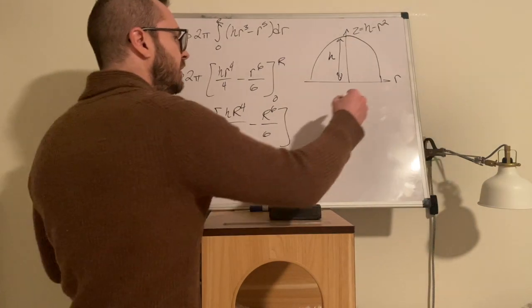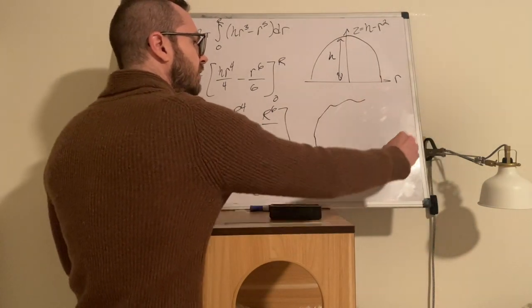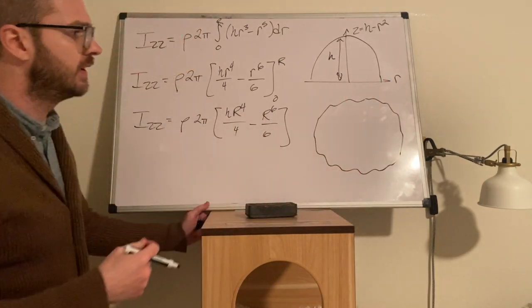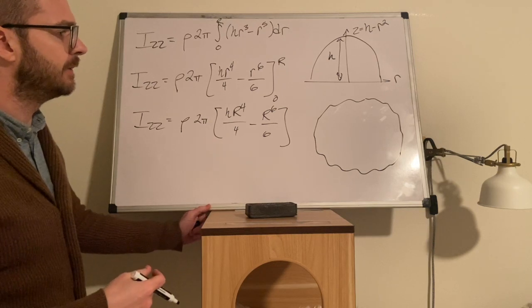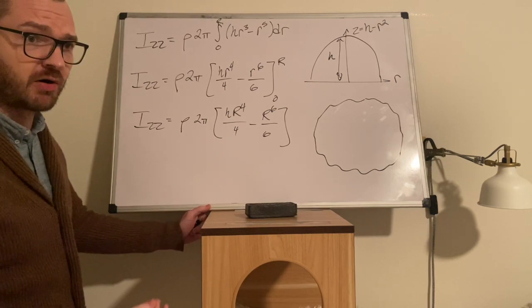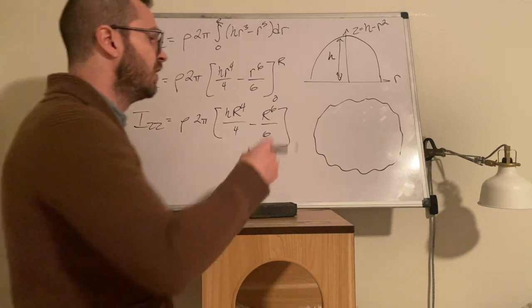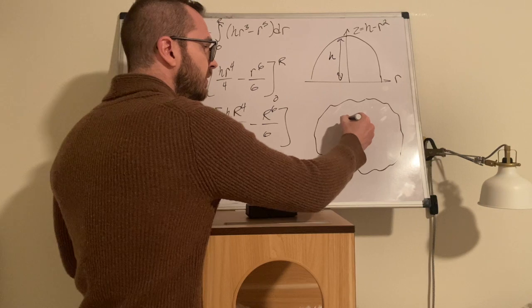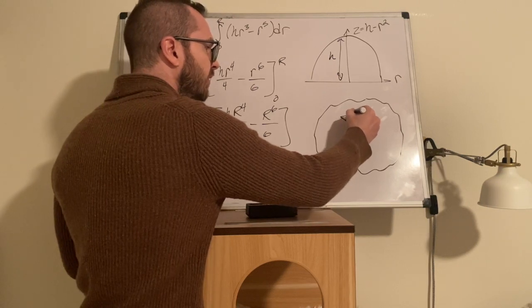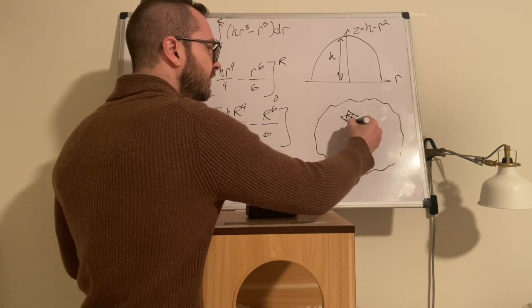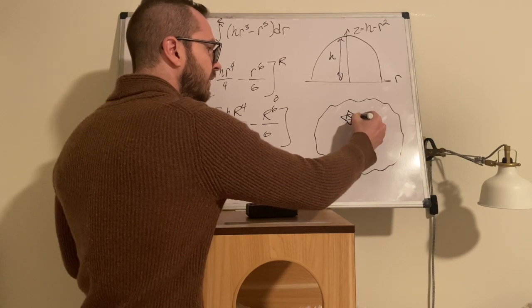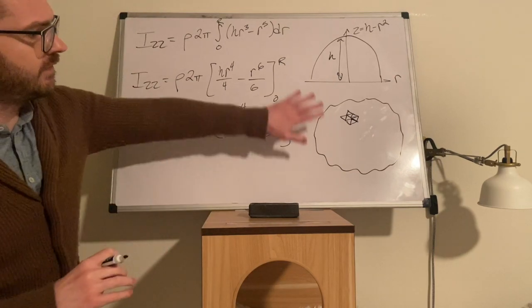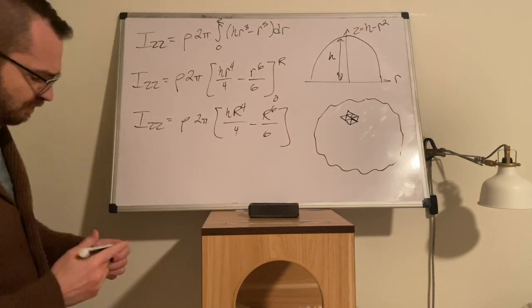And if you have some strange-shaped body, and this is not defined with some given functions, it could be a structural part with all kinds of material bored out of it. What really happens in CAD software is it takes this geometric shape and it breaks it into all of these discretized sections using nodes. And when it does that, it covers this whole geometric shape in a mesh.